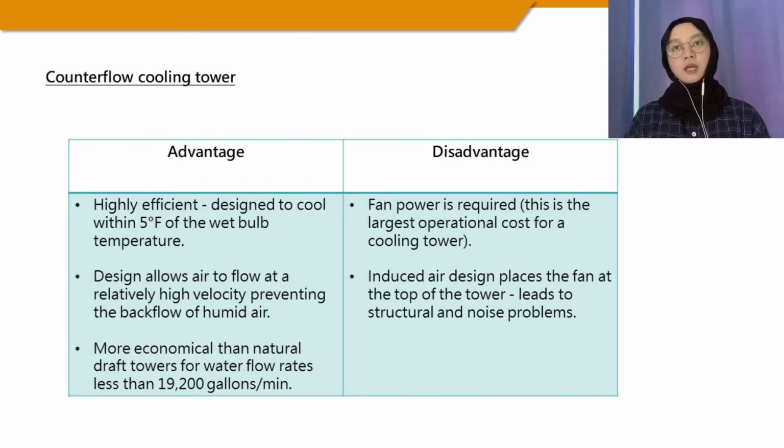Counterflow cooling tower advantages: highly efficient. The design allows air to flow at a relatively high velocity, preventing the backflow of humid air, and is more economic than natural draft towers. And the disadvantage of a counterflow cooling tower is that fan power is required, and the induced air design places the fan at the top of the tower, leading to structural and noise problems.